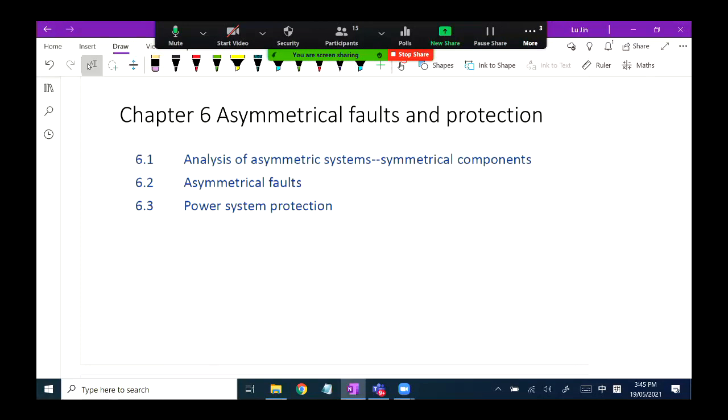If you want to draw the equivalent zero sequence circuit for the transformers, each transformer has two sides, and each side has two possible connection patterns, delta or Y. For the Y pattern, there are two options: neutral connected to ground, or neutral not connected to ground, or neutral connected to ground through some resistance or reactance. There are so many options and so many possibilities.